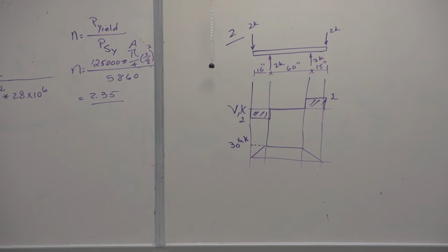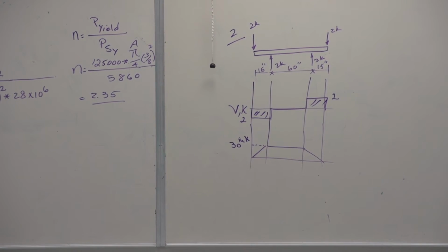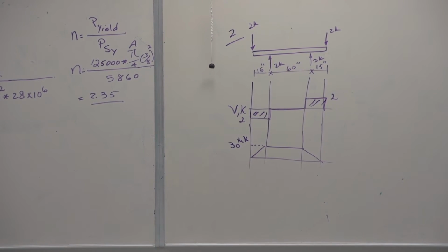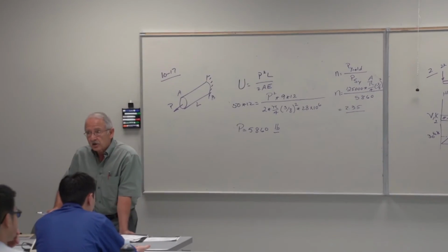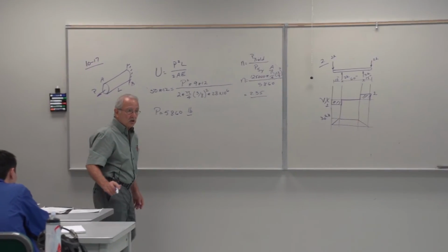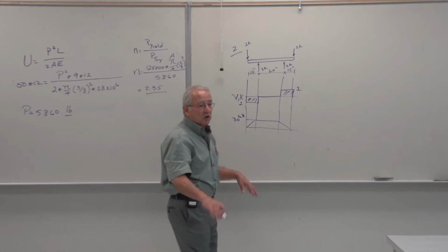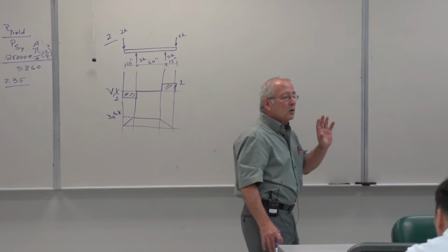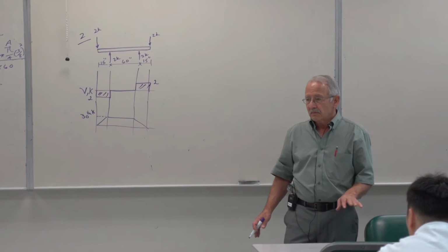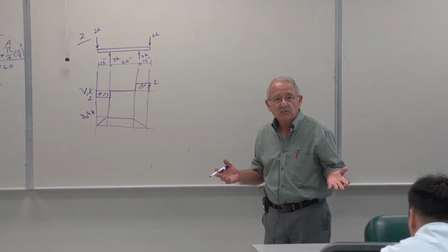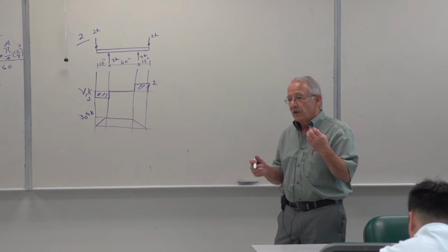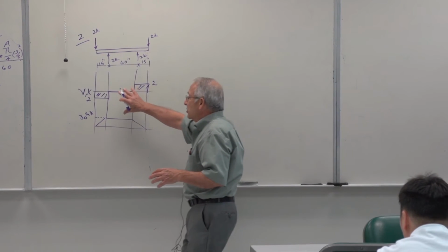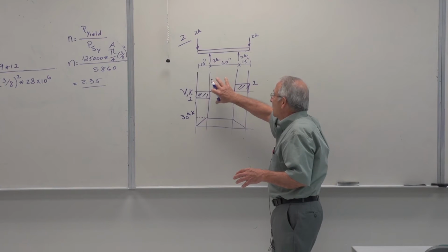You do not need to draw shear and moment diagrams for these problems. In fact, because in most problems we neglect the transverse shear contribution to the strain energy, you don't even need a shear diagram. Don't draw a moment diagram either, because unless you find the equation, the moment diagram by itself isn't going to do you any good. Therefore, although I've done this just to show you how this is, but here's what we do.